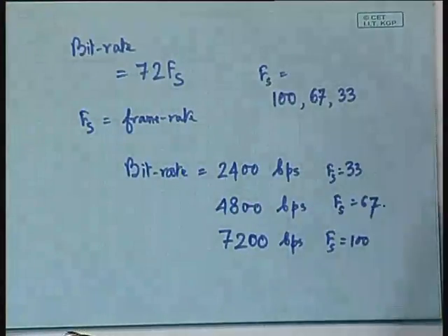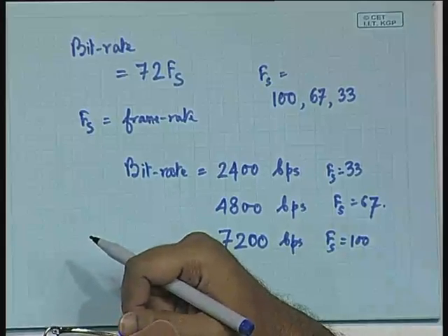So essentially a good pitch estimation is a requirement in order to have a proper synthesis, and unless the pitch parameter estimation is proper, the performance of the vocoder really suffers. So this leads us to conclude that really speaking, the pitch period estimation is normally the weakest link in an LPC vocoder.